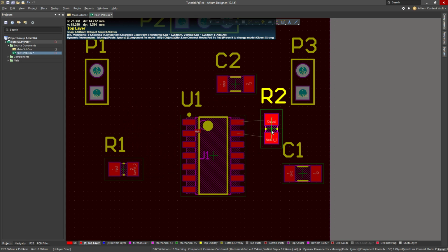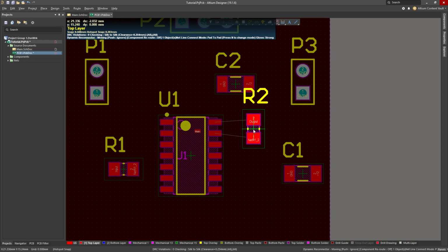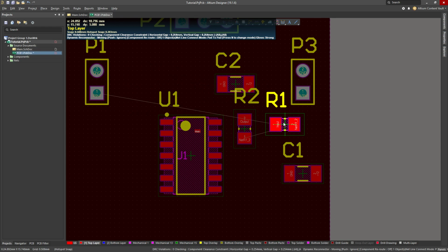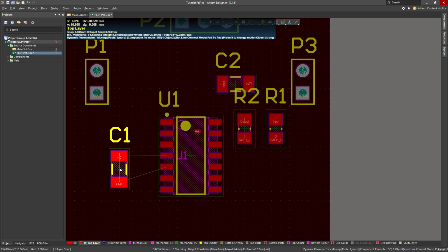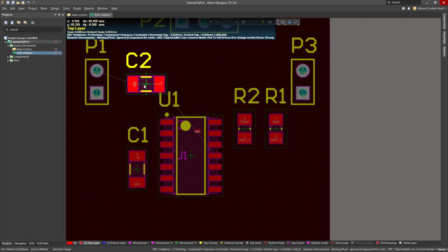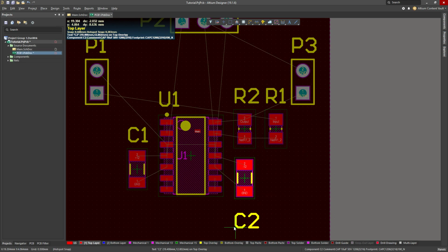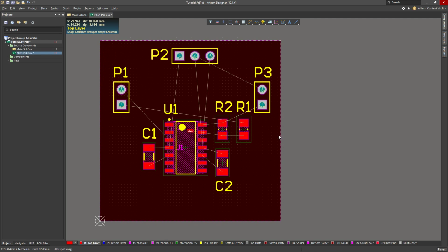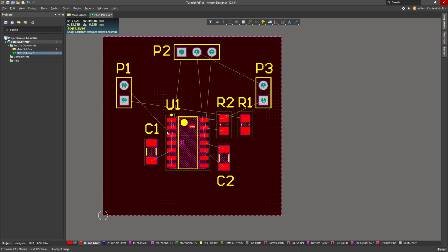So for example, this resistor needs to go towards, say, this side of the integrated circuit, so a good position would be to put R2 somewhere there. This one also connects over here, so that would be a reasonable place to put that component. My capacitor here I will put on that side, and this one can go, say, here would be a reasonable place for that, so that the air wires are fairly nicely not crossing over. So that's the layout that I'm going to use for this.